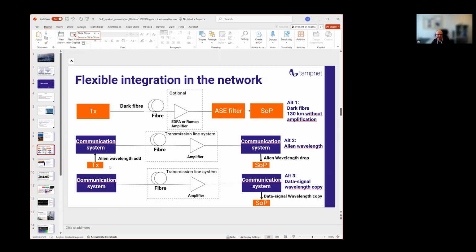Again, we just use an SFP with a laser sending a continuous signal. And by sending a continuous signal, not an on-off keyed signal, you get no interference problems with non-linear effects through the transmission system. So it's actually quite important not to send on-off keying. If you send 10 gig on-off, it may be interfering with your high bitrate communication channels.